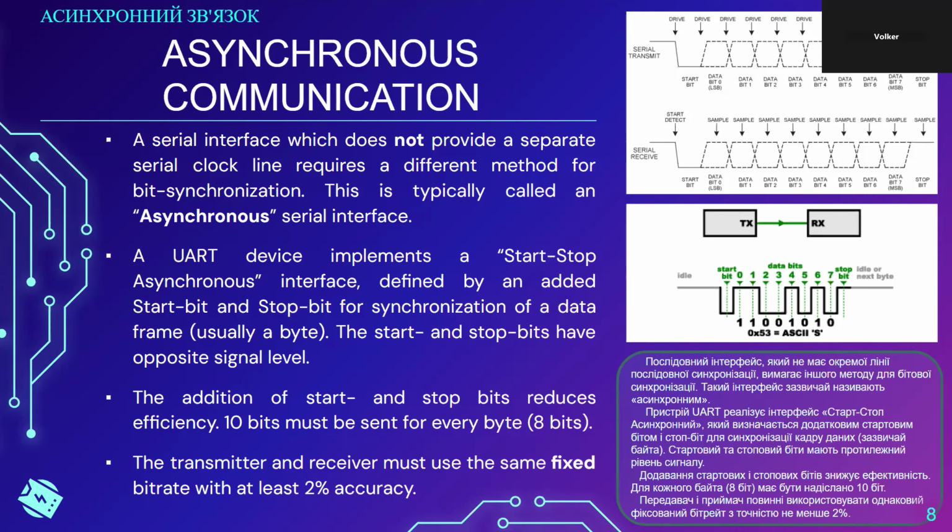The next consequence of this is that the entire system, sometimes, especially in older microcontrollers, is driven by this need for the fixed bit rate and by the 2% accuracy, meaning that when you're looking into circuit board crystal oscillators, you will sometimes find very strange crystal frequencies.